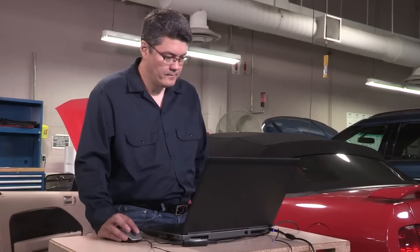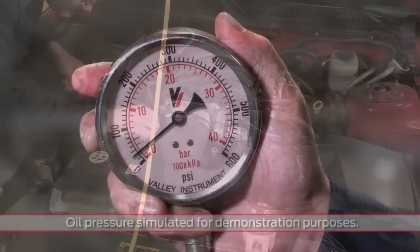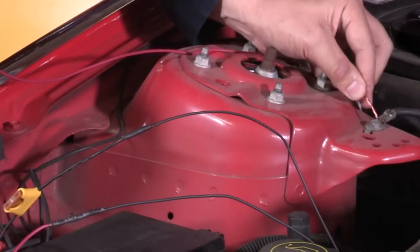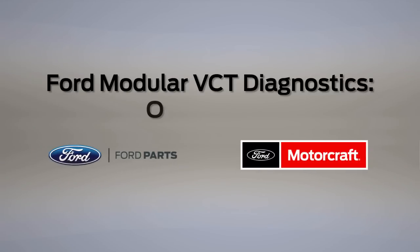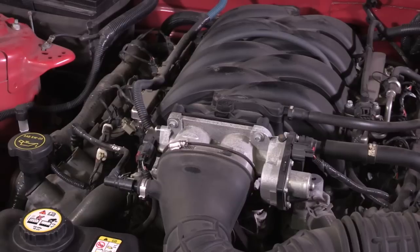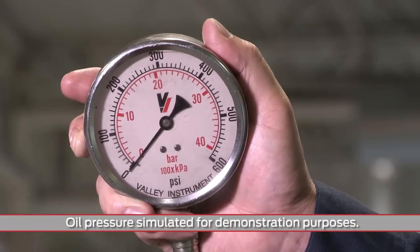When diagnosing VCT issues, it helps to take a systematic approach by exploring 4 main areas of investigation: oil pressure, excessive oil bleed-off, a restriction in the oil passages, and mechanical failure. The modular engine needs proper oil pressure to maintain control of the variable cam timing or VCT system. When the VCT loses control, even though the engine oil is at the proper level and in good condition, start by checking the oil pressure.